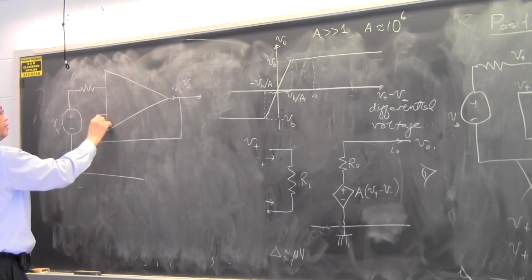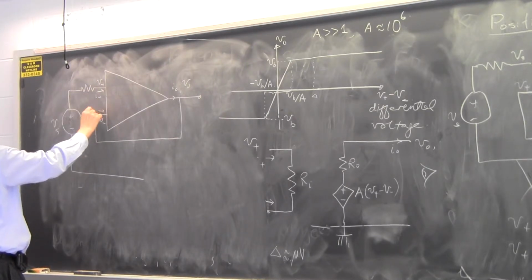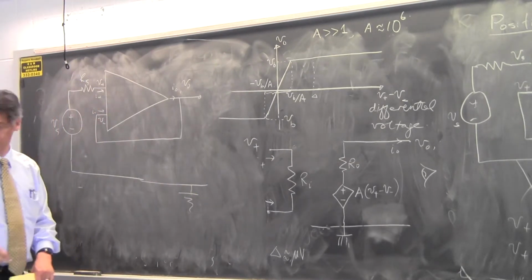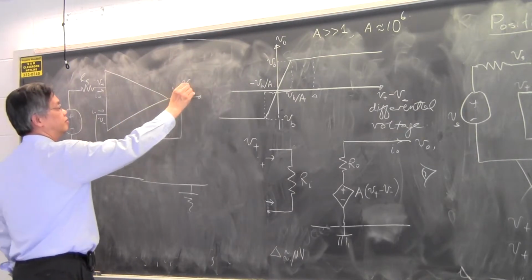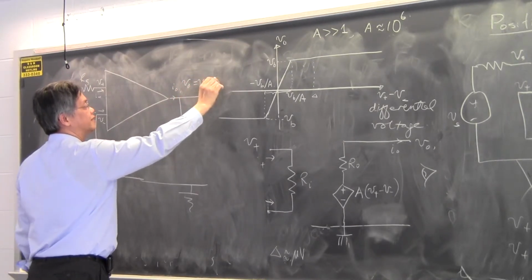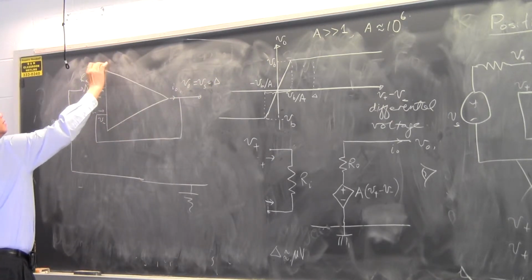And then this is V minus, V plus, this is I plus, this is I minus, this is R source. And this is a voltage follower, and that one works, but that one doesn't work. And let's examine the reason why. Let's assume that V0 is equal to Vs plus delta, or minus delta. It has to be slightly lower. V0 has to be slightly lower than Vs.